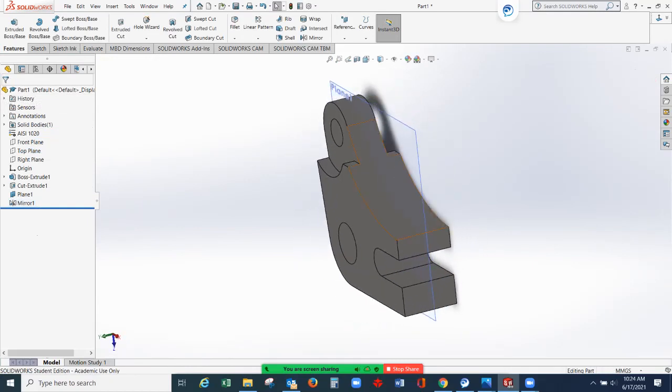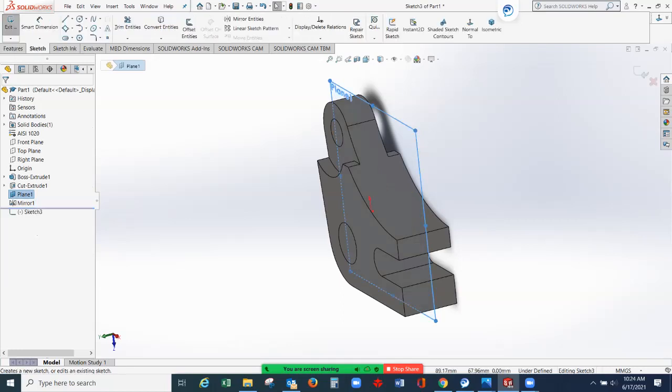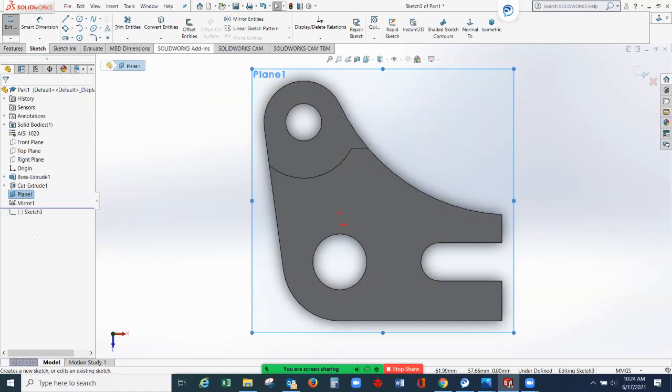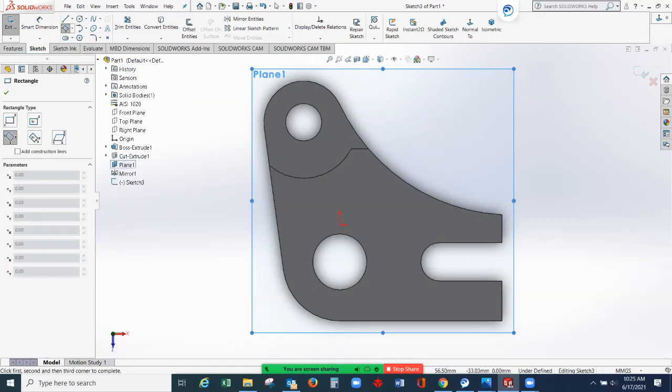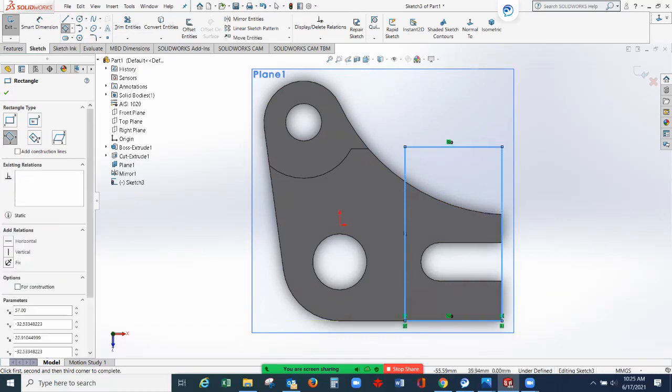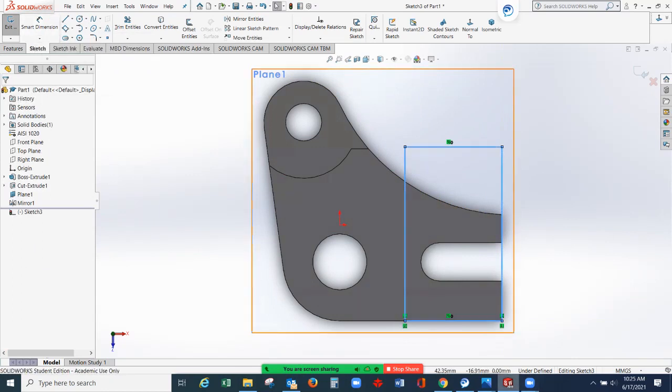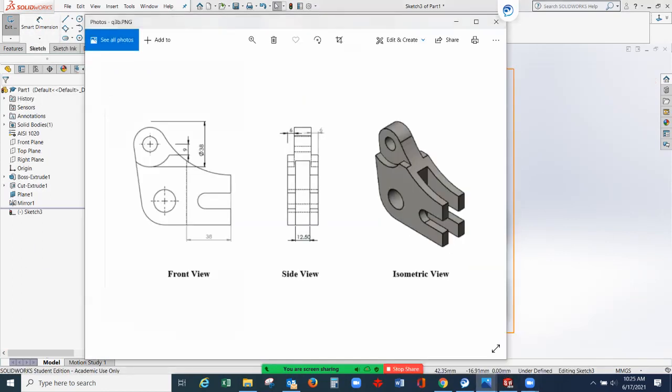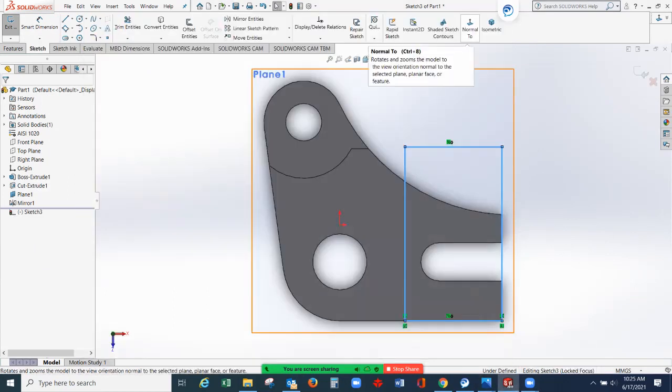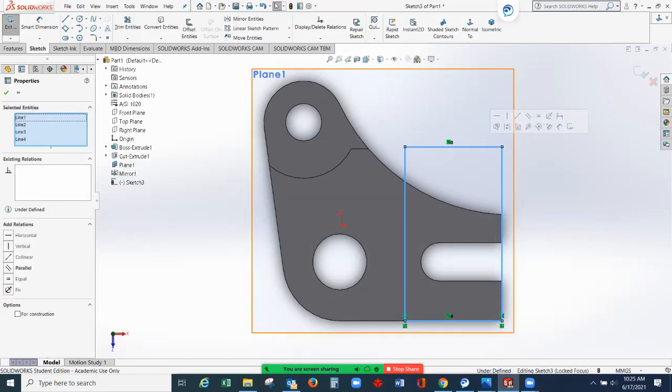And then here we have one more cut on the middle. So we're using also this reference plane. From this reference plane, select this, Control 8, and draw one rectangle. So for example, 3-point corner rectangle. From here up to here, then move up, select the green check mark, then give the dimension. So the cut is 12.5, the distance is 38. So this distance is 38.